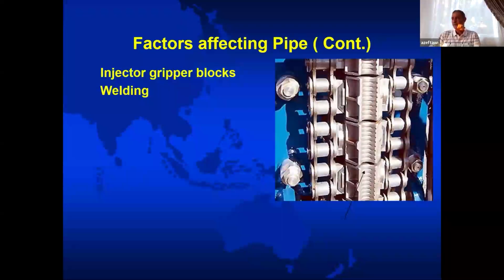How do we manufacture the pipe? Well, the pipe comes as strips from the mill. And these strips, we cut to a width corresponding to the size, the diameter we need. And then these strips normally come in rolls of maybe 4,000 feet of length.